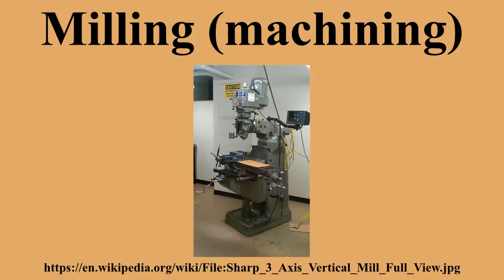A computerized form of NC machines is known as CNC machines. A set of instructions is used to guide the machine for desired operations. Some very commonly used codes, which are used in the program, are G00 Rapid Traverse, G01 Linear Interpolation of Tool, G21 Dimensions in Metric Units, M03, M04 Spindle Start, M30 Program End. Various other codes are also used.